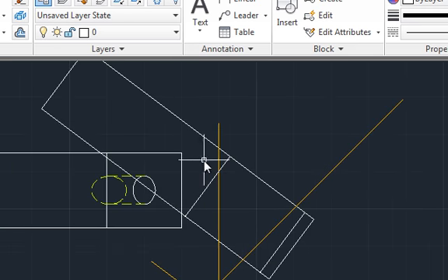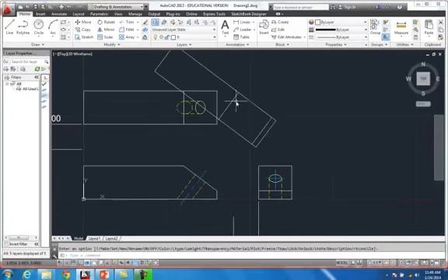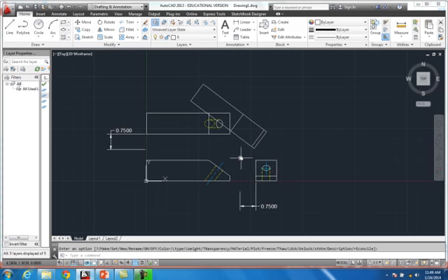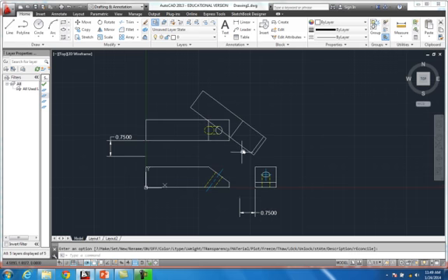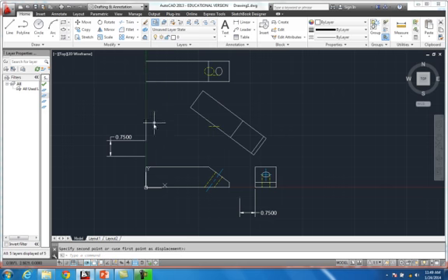All right, that is the auxiliary view. Now this right here is the true space, and I want to go in here and hide this fold line just for a moment. Now, you're asking me probably, after we get this thing drawn up, we could probably be best if we took and just moved this view up just a fuzz, just to get it out of the way. Then we can readjust a few things in your drawing.